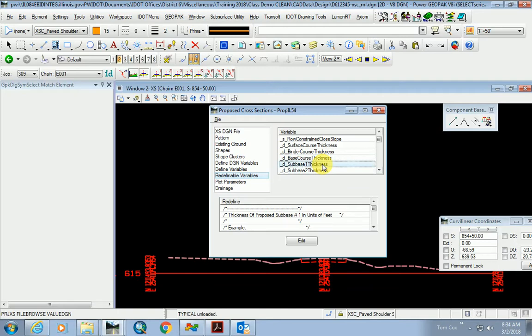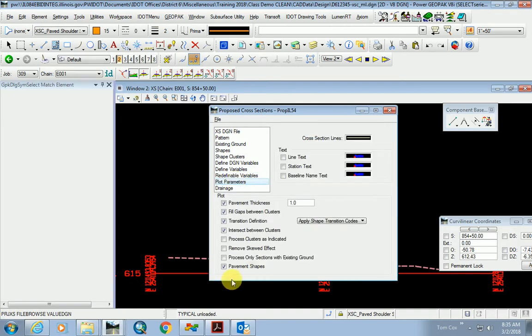And then sub-base. That's normally an aggregate sub-base, usually 8 or 12 inches. Or it's going to be like a lime modified soil on new construction on a rural section, and that might be like 12 inches. But again, we're not using that in this case, so I'm going to end up deleting those, even though it's going to draft those. We'll just leave that as is.